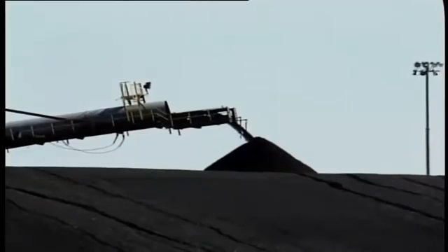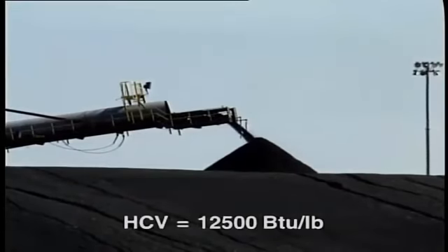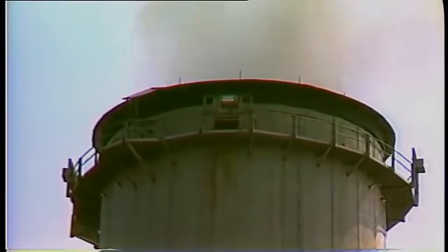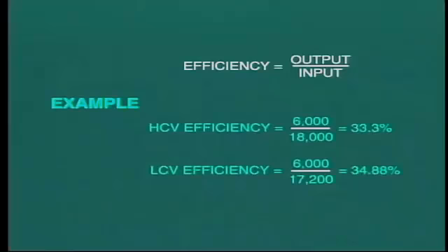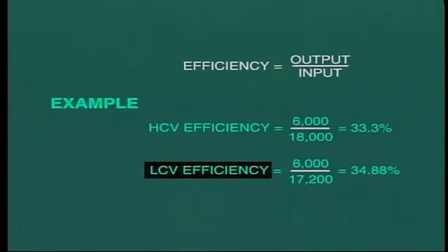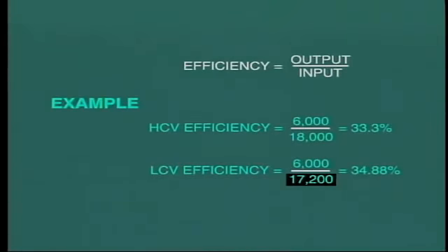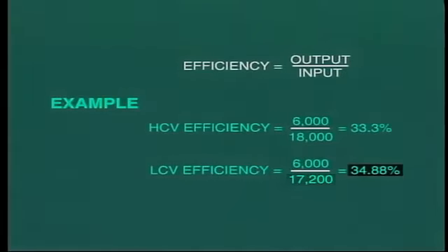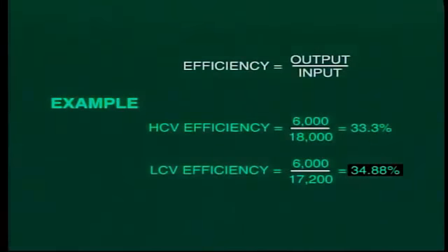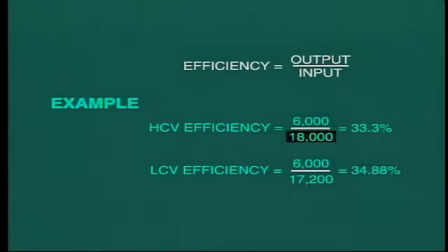In the USA, it is usual to quote the higher calorific value. The logic of this is that we have to purchase all the fuel even if some of the heat cannot be recovered. In fact, as we know, other heat losses are far greater than this amount. However, beware, in many other situations, for example, in many European plants and European manufactured equipment, the quoted efficiency is based on the lower calorific value. This would, of course, provide an apparent higher number for efficiency.